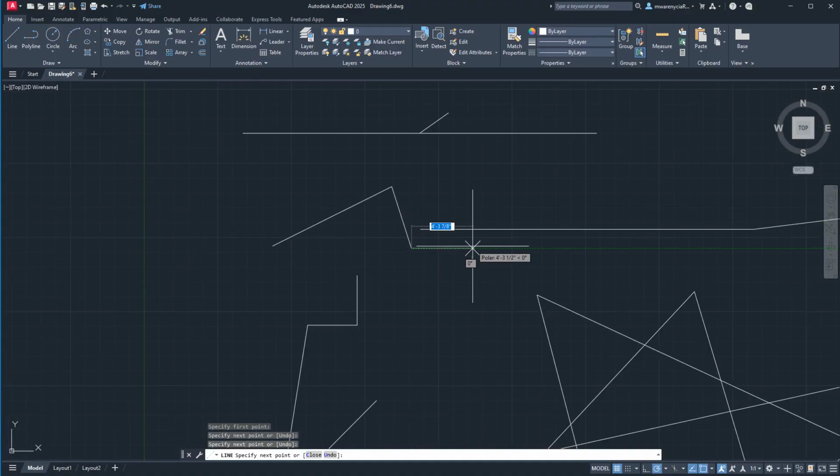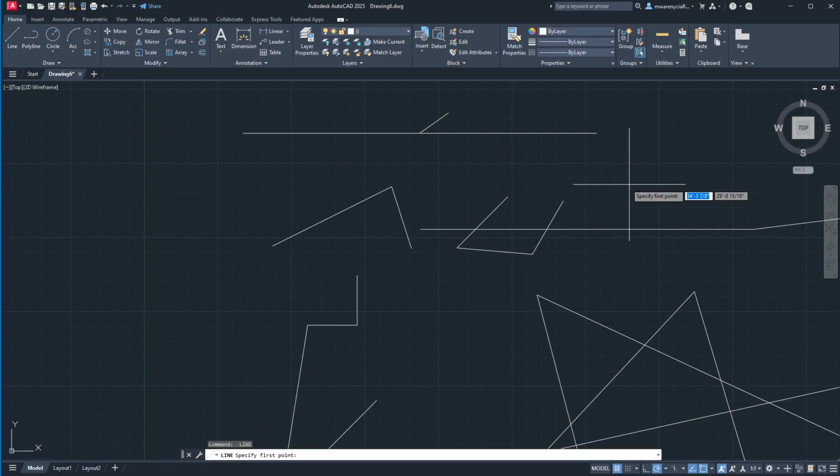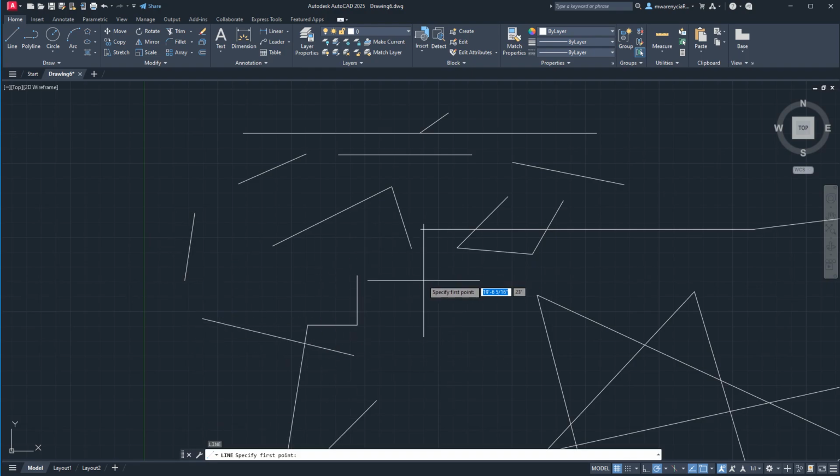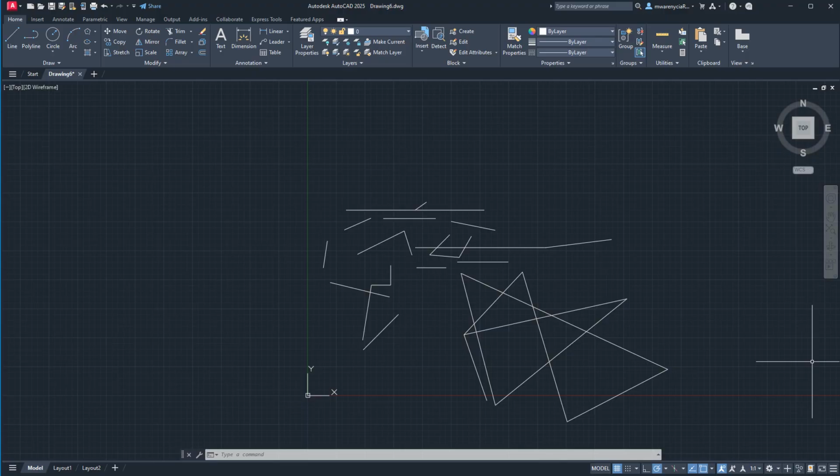And then if I want to stop using the line tool, I can hit space bar again. It'll stop the tool. And if I hit space bar again, it'll resume the tool. If I want to do a series of lines like that, I can keep toggling the tool on and off with space bar without having to do L, enter, hit escape, come back up here, do that, hit escape. I think it's very convenient placing for your left hand to be in that area, and you can work a lot quicker with a lot of these tools. So zoom, line tool, spacebar.